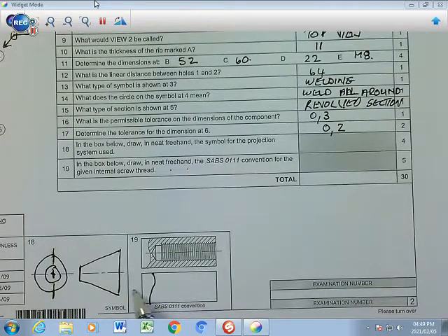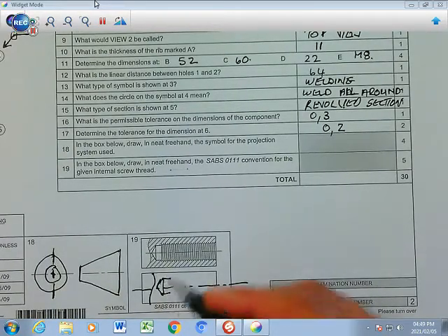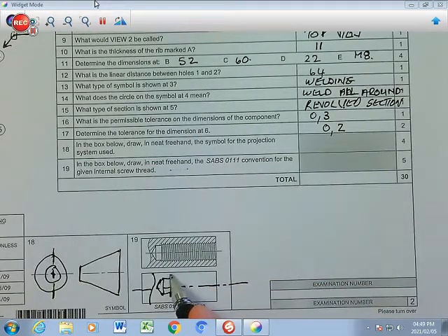So now we're going to draw a center line through the middle first, and the center line is a long short chain line, and then we're going to draw these bottom parts like that first, connected like that. That's that part over there, and then we're going to put a wider section there and draw it till there like that on both sides. And then of course here you are going to draw the double lines in line with that there, and the double line in line with that there, right? And then you are going to hatch everything there, right?